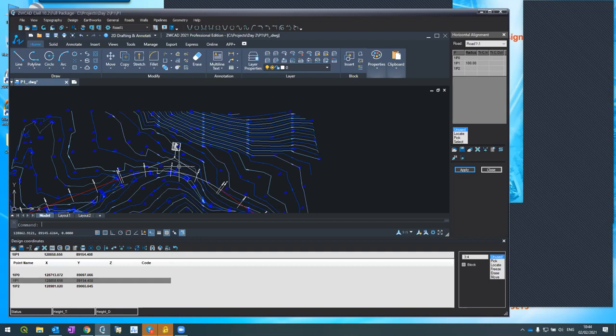If I want to create defaults, I change it in the prototype. In this case, my prototype was white. But if you go to prototype, you do file, open prototype, and then in the drawing, there's a file name there, prototype_DWG. You change the colors there. Whenever you create a new project, the system will inherit the colors from prototype. So the answer is, in my example here, I used my own prototype. But usually when you do default, it will be with blue by itself. Okay. I hope I answered this question.